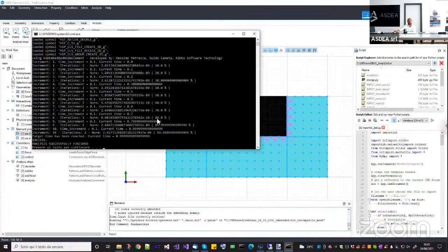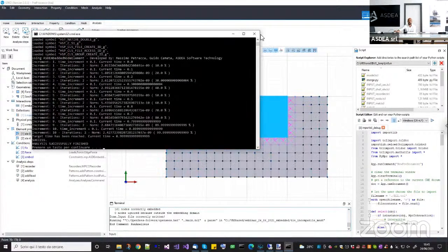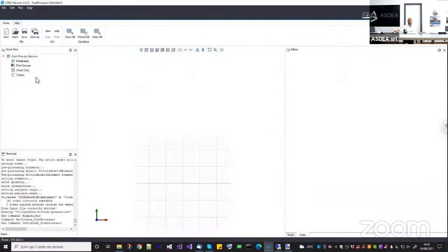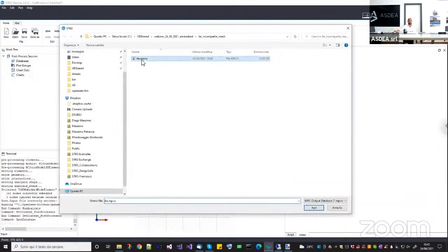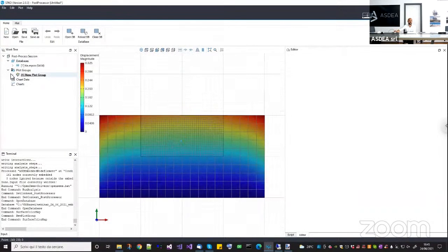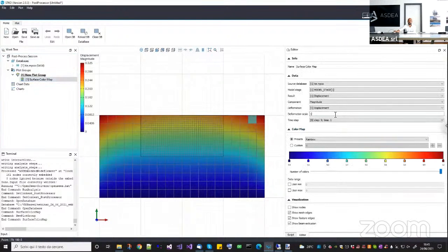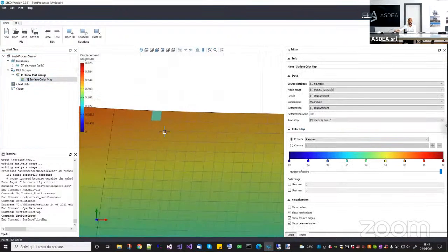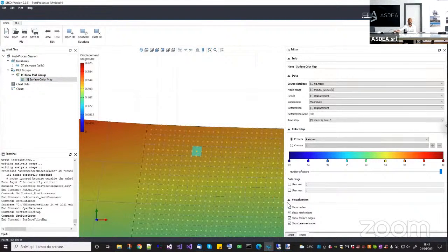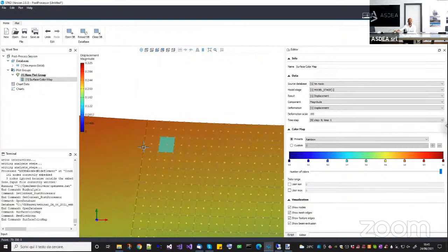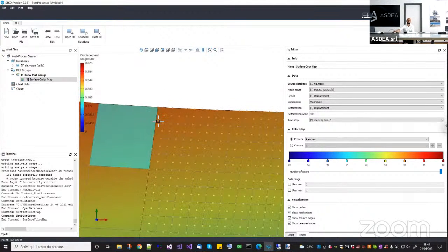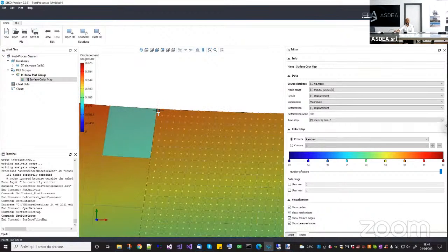Of course, it is a little bit more expensive because the quadratic element is much denser, but you can do it. Here it is. And let's see it in the nodes, so you are sure that it is a quadratic element, as you can see here. So the nodes are perfectly attached. So there is no difference, because actually my constraint is attaching a node to an element. So it doesn't care what kind of element it is, okay? Because the source is a node, and it doesn't care where this node belongs to.